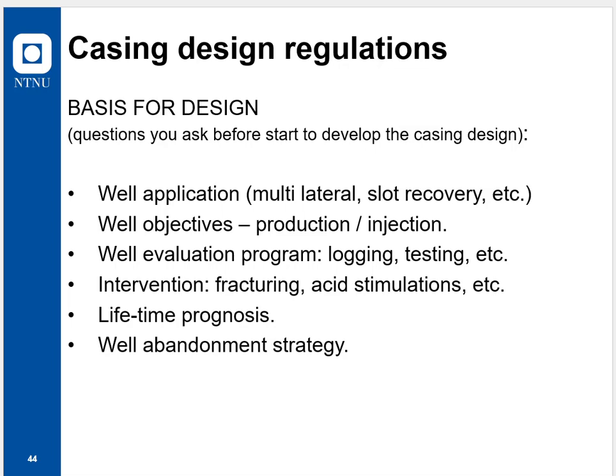Then we always need to do a life cycle design. So we need to know, is this a well that is going to stay for 5 years or for 15 years? All components of the well need to be analyzed in this regard, even the casing, hanger and wellhead system, the lifespan of each component in the well. And then finally we also need to understand what is the company well abandonment strategy.